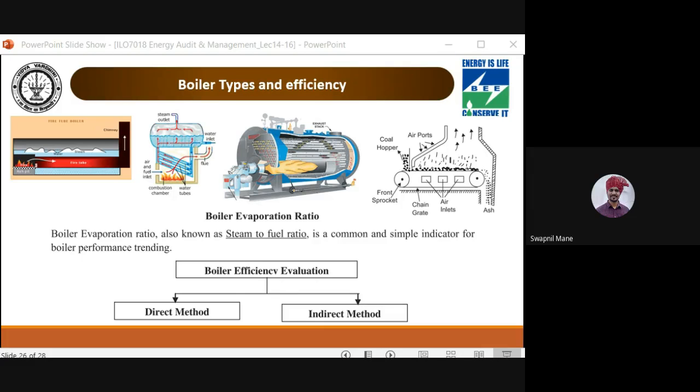These suspended particles look like a gas or finely meshed particles undisturbed at low velocity, and this air velocity is gradually increased until a stage is reached when the individual particles are actually suspended in the airstream. Further increase in the velocity will give rise to bubble formation or vigorous turbulence and rapid mixing, and the bed is said to be fluidized.